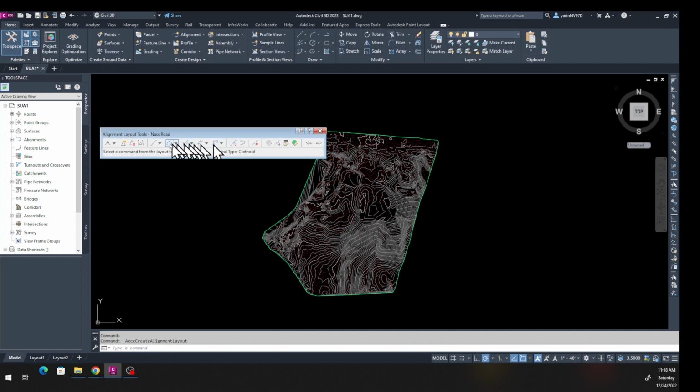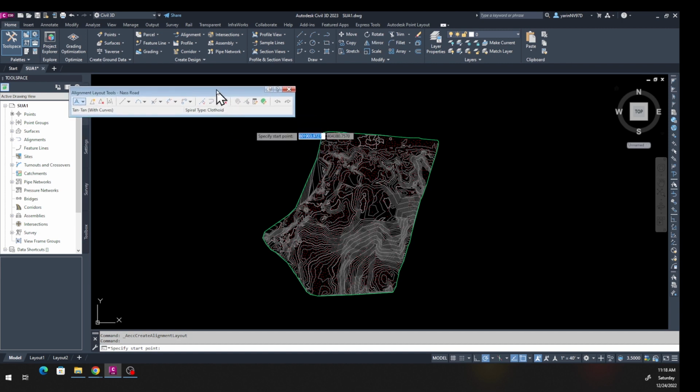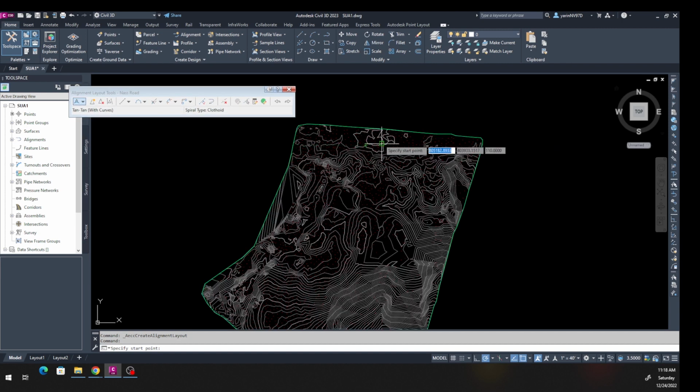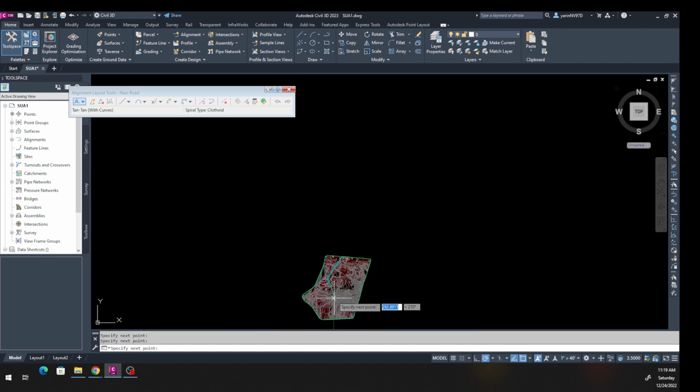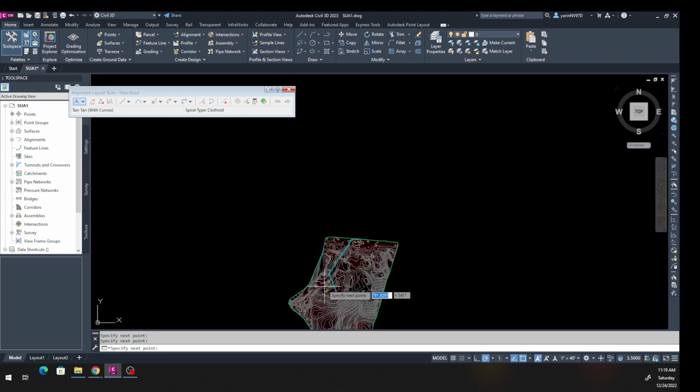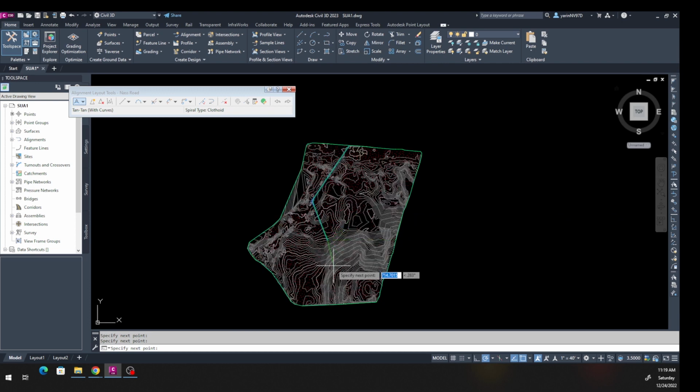And then come back in here. Let's identify the curve setting. I'm going to come up here from this left corner, say tangent with curve, and there we are. Now we are in a mode where we can go ahead and make your own road and have fun with it. I'm going to start from here, try to hit as many alignment points as I can. I'm going to come up here and take a turn back in here and keep going. Whoops, the other way. Come on, don't freeze on me. And then come back and finish it up right here and click OK and hit enter. So put some curve in there.